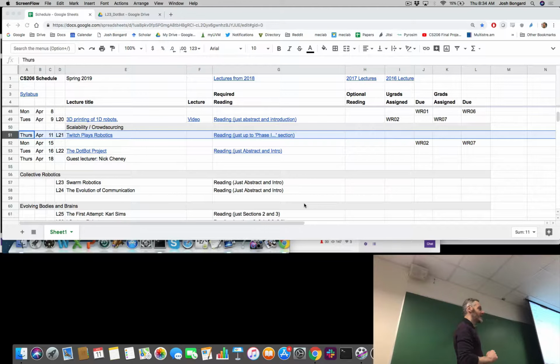So the way to do that is before you start evaluating your controllers in the first generation, you create your random environments randomly, and then everyone sees the same set. So no one controller can get more lucky than another one. You're kind of leveling the playing field. Okay, it's a common technique that's useful if you're trying to estimate the mean performance of your robot in randomly varying environments. Make sense?